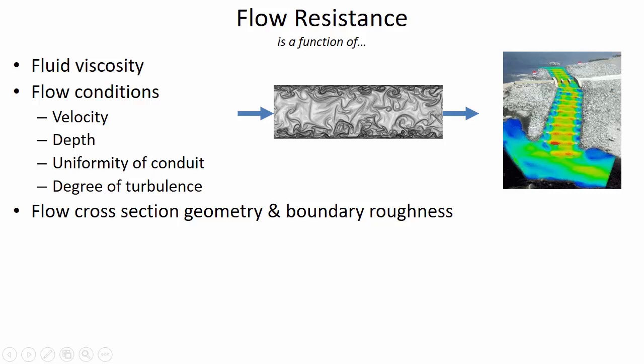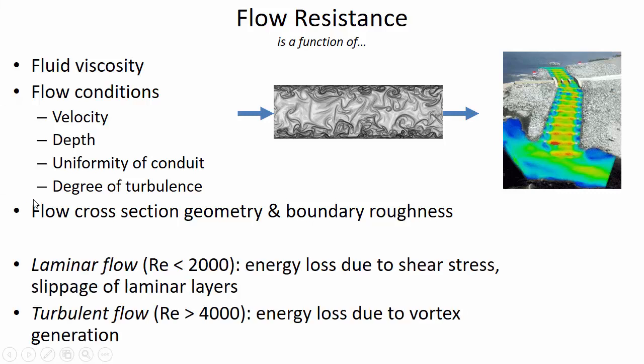And so remember that in fluid mechanics, when we were doing the experiment having to do with the Hazen-Williams equation, one of the reasons why the Hazen-Williams equation didn't give us maximum accuracy is it didn't take a lot of these factors into account. Now, the Hazen-Williams equation is calibrated for just a certain temperature of water, but if you have water outside of that initial calibration, then there's no adjustment for viscosity. The Darcy-Weisbach equation, by contrast, does take all of these factors into account, including whether the flow conditions are laminar or turbulent. Does anybody remember the formula for the Reynolds number?